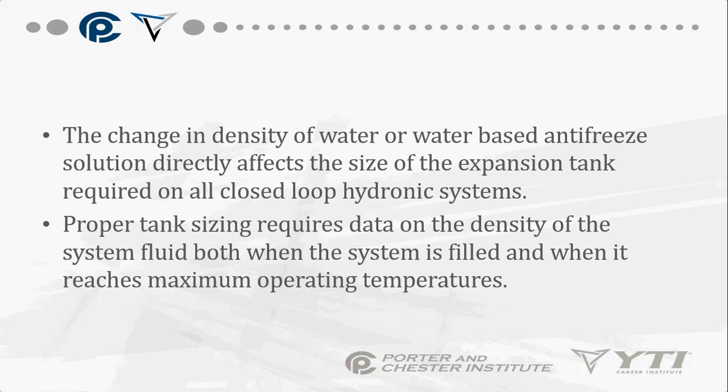So when a boiler is heating up, and we're heating up the water in that system, that water is going to expand. Remember, the molecular structure of the water, it's going to expand. Now remember, a boiler is really a sealed system. I have to have some space where I can allow for that extra expansion to go, so I don't start rupturing pipes.